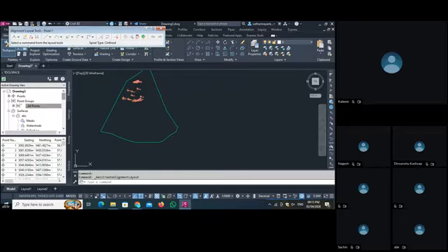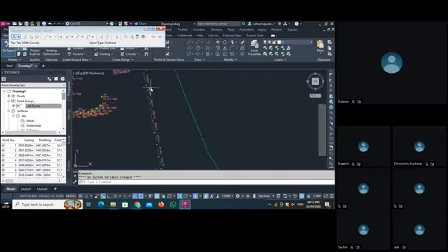In this layout tool, we open the first option here and select the tangent with curve. As we select this, we click here, we set our alignment. If you want to end this, you can press escape or enter. So your alignment is created with all the details.